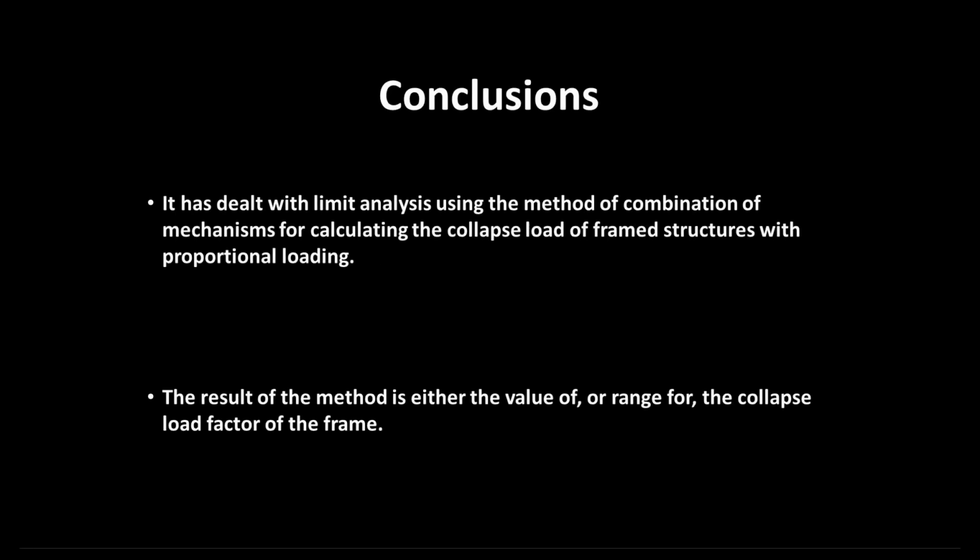From the conclusions, what we learned: it has dealt with limit analysis using the method of combination of mechanisms for calculating the collapse load of framed structures with proportional loading. The result of the method is either the value of or range for the collapse load factor of the frame.